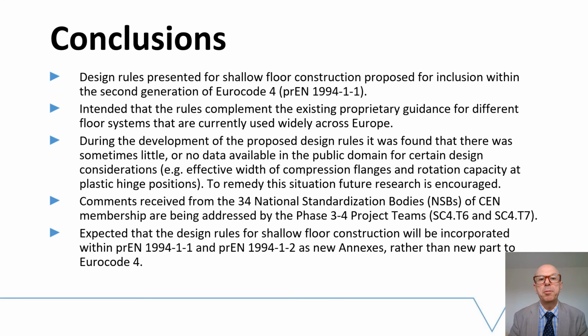However, during the development of the proposed design rules, it's found that there was sometimes little or no data available in the public domain for certain design considerations, such as effective width of compression flanges and rotation capacity at plastic hinge positions. To remedy this situation, the project team would encourage future research in these areas.